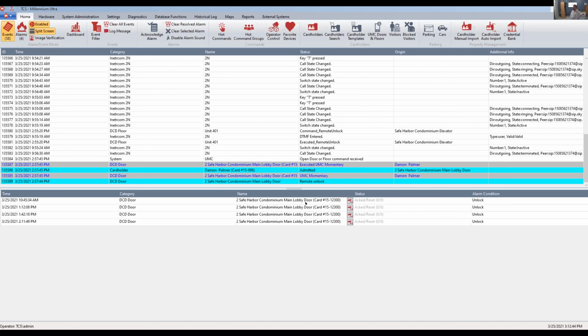But sometimes it's actually cleaner and more reliable just to use 12-volt supplied by a line-conditioned power supply. Plus you can do several devices. You can do that with the PoE as well. But yeah, if you've got a good PoE, I guess that would be fine. But then you'd have to buy a converter for each one. So maybe the cost would be there, maybe it wouldn't.